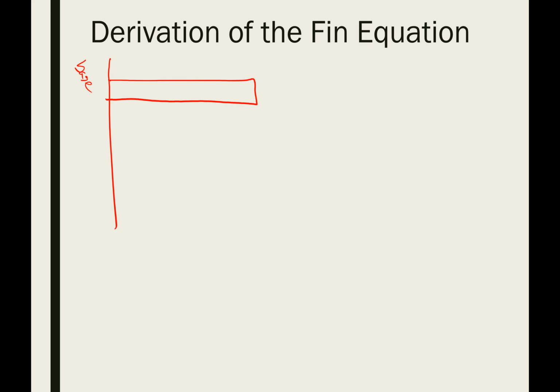So this problem, we're going to make it a one-dimensional problem. And we're going to do that by assuming that temperature varies only in this direction. Let's call this the x direction. So if we want to be as rigorous as we can possibly be, is this really a one-dimensional problem? So why not? Okay, I see Titus showing that temperature is probably going to vary in this direction as well. So we're basically neglecting temperature variation in that direction.